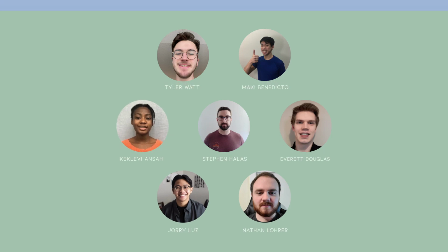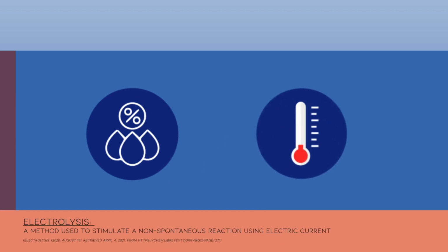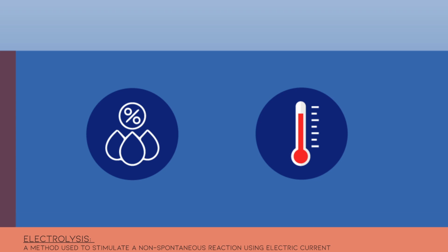This is how it works. We have the DO sensor that uses the principle of electrolysis to measure the DO, and the temperature sensor to measure the temperature of the water. This then goes back to the brain box to calculate how much air is needed to pump back into the system. This information is then used to control the compressor.